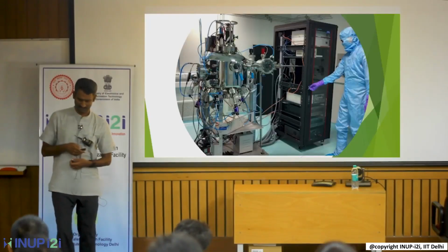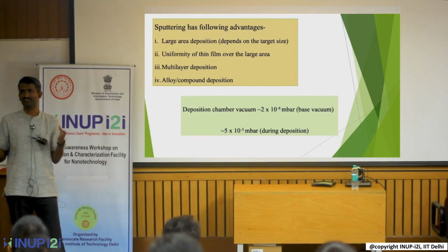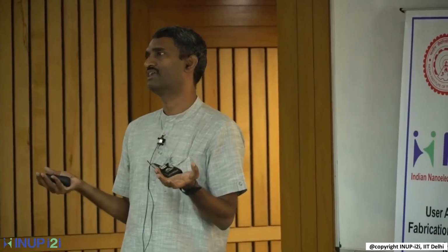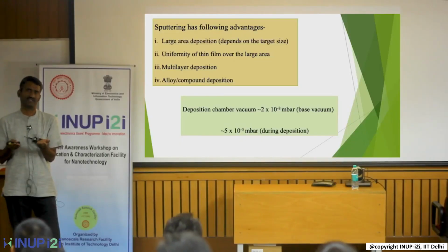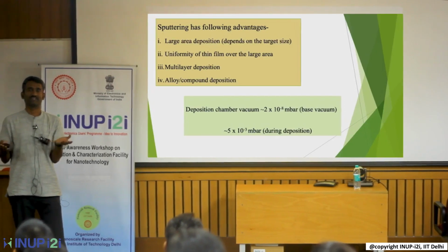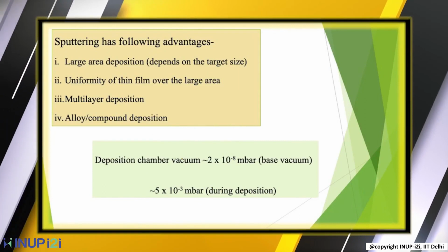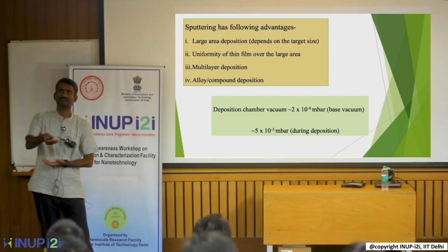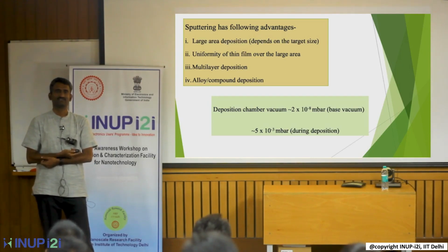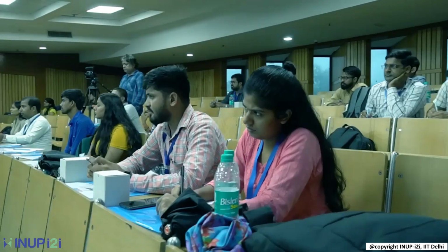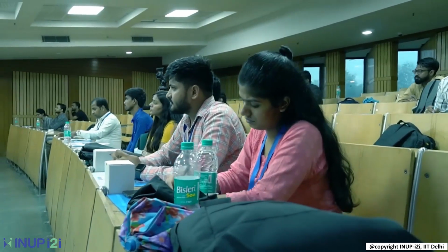So you can make it using this type of sputtering system. Because now we are playing with functional materials to fine-tune the optical and electronic properties. So we are not only interested in simple gold, silver, or other single-element semiconductors or metals. We would like to take advantage at various levels by incorporating some percentage of doping, to change the carrier concentration or improve the electrical, magnetic, or optical properties.